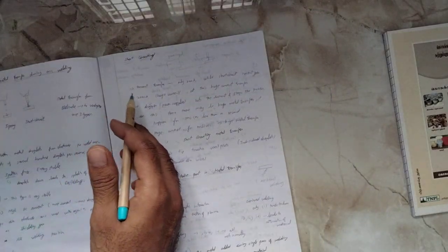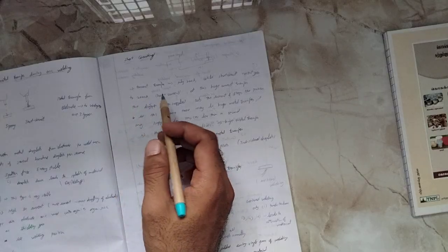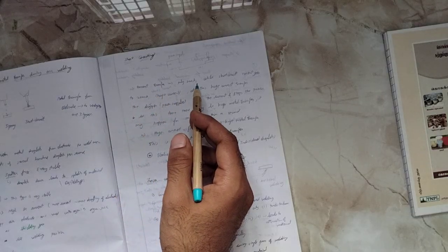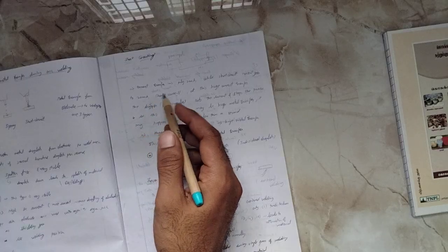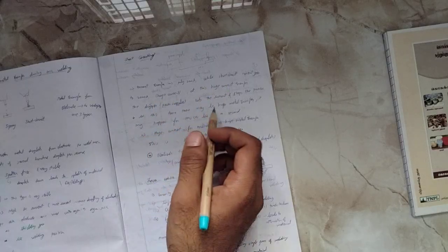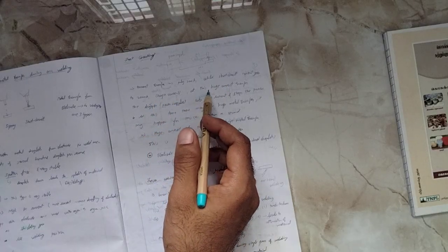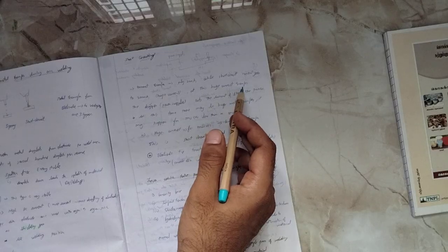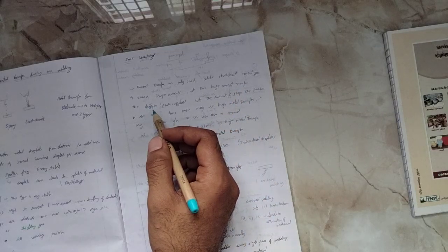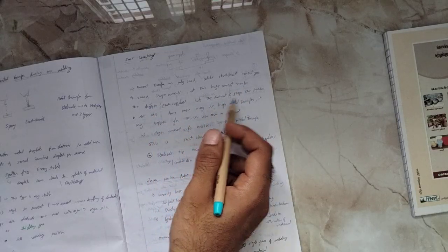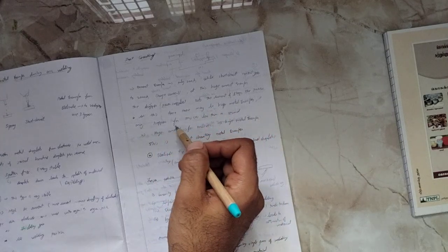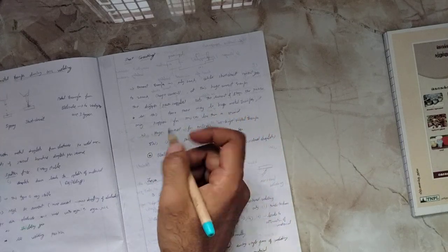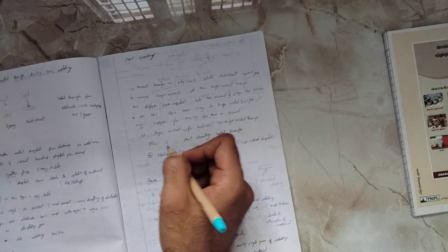Due to the short circuiting, a lot of transfer occurs. You can see the current is only 200 amperes, but when the short circuit comes, it goes to 2000 amperes. Because of the voltage drop as well as the pressure drop, the current drops. At this huge current transfer, a drooper power supply will be used, which cuts the current and stops the process. At this time there may be huge metal transfer, and it may happen for just 1 millisecond. So huge current flows for 1 millisecond, with huge metal transfer.